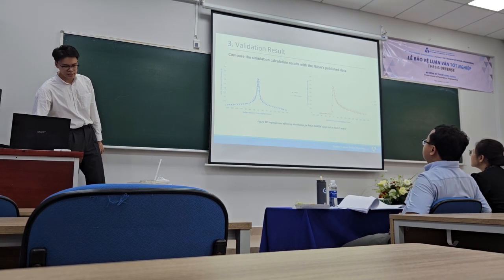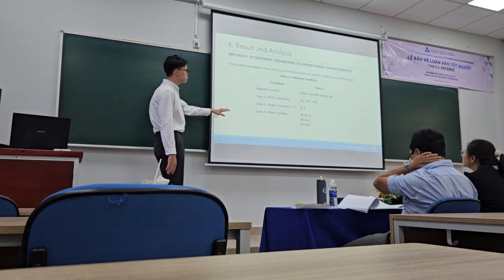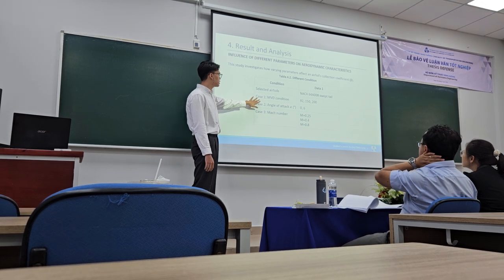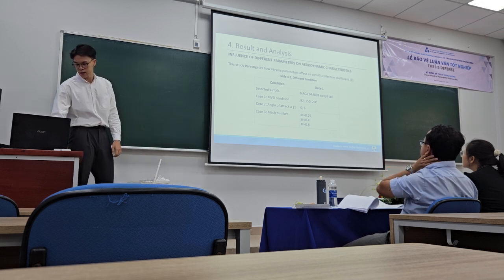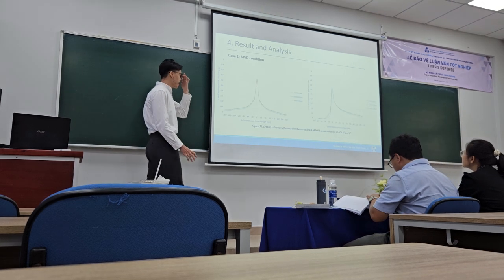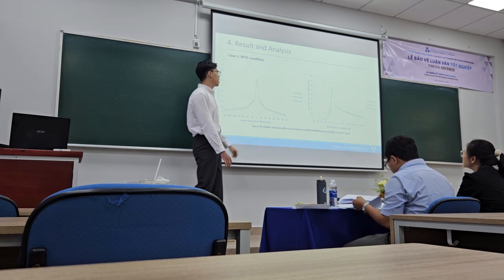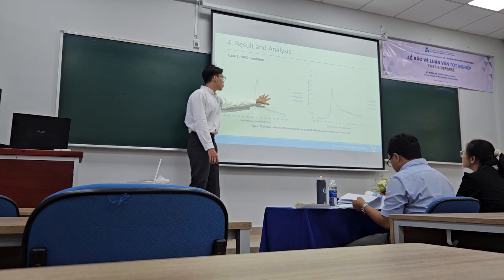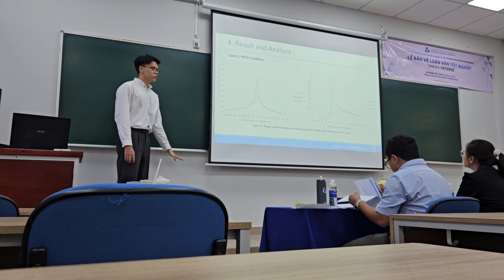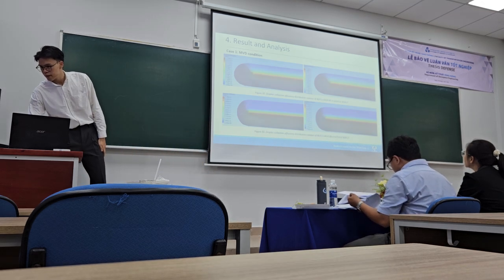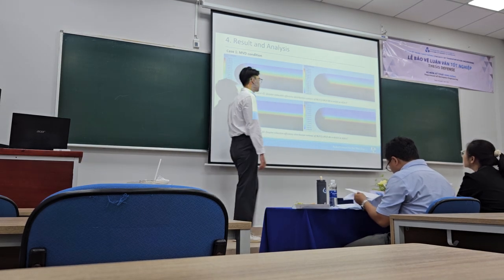This is for collection efficiency. And come to the cases, this is also similar to the 2D model. I will also change the MVD, angle of attack, and Mach number to see the difference between them. And it shows the same change: with the higher medium volume diameter, we get higher collection efficiency on the airfoil surface. As you can see there, the yellow line is the biggest volume diameter, equal to 200 micrometers. And this is the contour. You can see the difference between them.